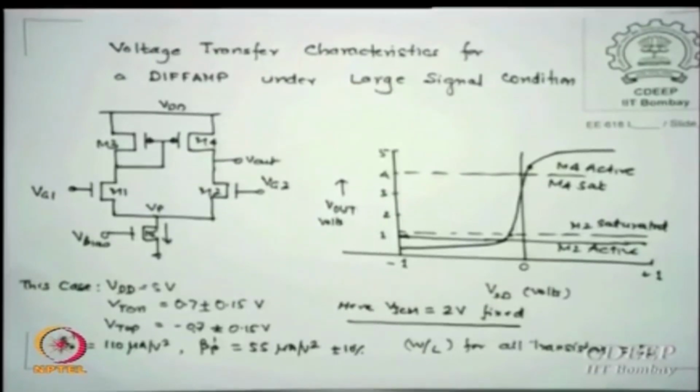We are not saying that this is specific to a technology. We may say okay, this is the data, or this is the spec. In reality SPICE will not allow you random numbers for a given node, they will specify each of them because their oxide thickness are known, their capacitance are known, they know everything there. So they will specify automatically these values which you do not have to even worry, but if you want to read, they will show you also what are the values they have been using.